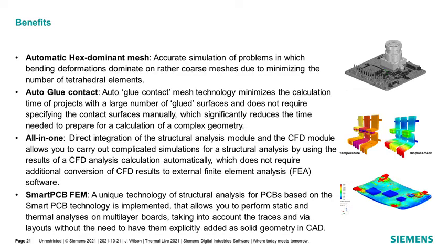We already saw the benefit, or discussed briefly the benefit, of it being CFD and thermomechanical all in one tool. So the way this process would work in SimCenter FloEFD, if you wanted to do your typical CFD thermal analysis, system design, and also the structural thermomechanical stress, you just specify that you want that analysis done after the CFD simulation has been completed. Then it automatically does the thermomechanical stress all in one environment.